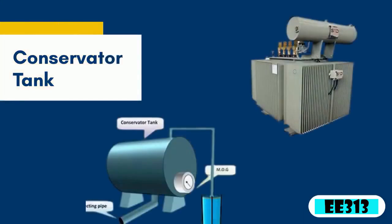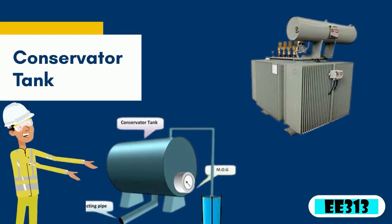The 10th component is the conservator tank, a cylindrical component that contains oil and absorbs swell from hot oil. This is located above the transformer tank and its main function is to provide adequate space for expansion of oil inside the transformer.